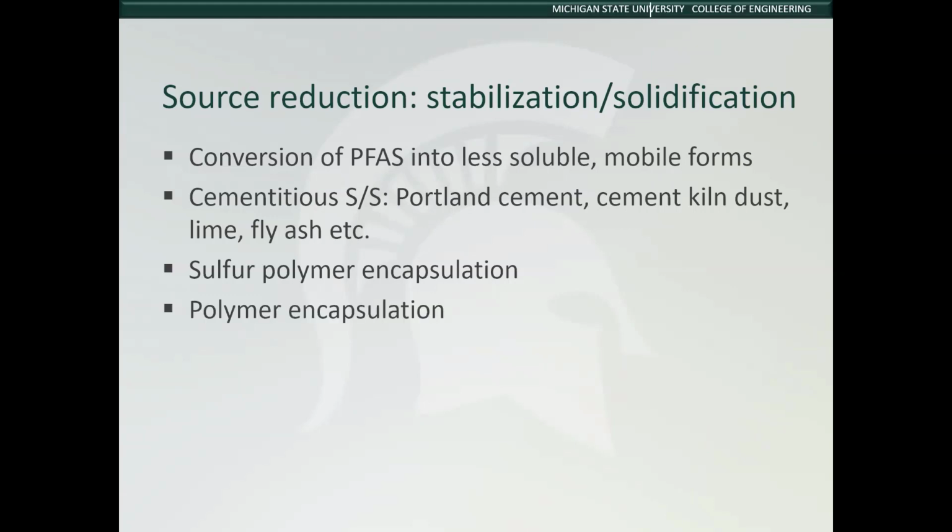Both thermoplastic and thermoset polymers have been successfully used to microencapsulate radioactive waste. Thermoplastic extrusion using low-density polyethylene has been used for polymer encapsulation of mixed waste. Thermoset polymers, including epoxies, are formed by a chemical reaction involving a liquid monomer and a curing agent. Metal catalysts have also been used.